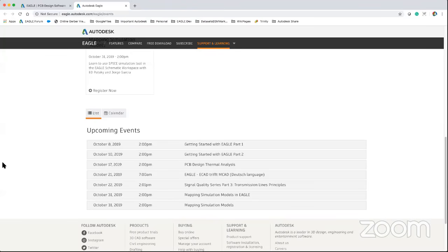So if you're building components and you want to get the 3D model for free, you can grab it from there and it'll come with it. That's pretty cool. They're all IPC compliant components, so they're pretty decent to use. It's called Reference Packages hyphen 3D. This is the name of that library. Just update; if you go into the Available tab, you'll see it there. I think new versions of Eagle ship with it as part of the managed bundle, in the managed library. I think it automatically installs or updates. If you already have Eagle installed, you have to go out manually and update it.